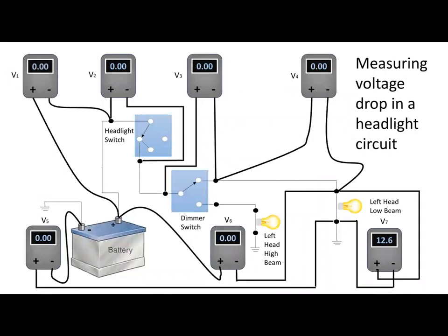For example, if the headlights become considerably brighter when the engine RPM is increased, this could indicate that charging voltage may be excessive, or that there are more amps being used by the electrical system than the alternator can provide at low RPMs. Normal charging voltage is between 14.2 volts and 14.8 volts with the engine at normal operating temperature.